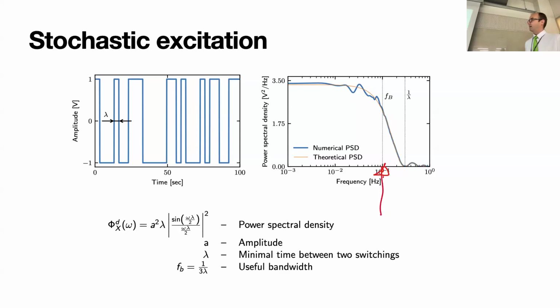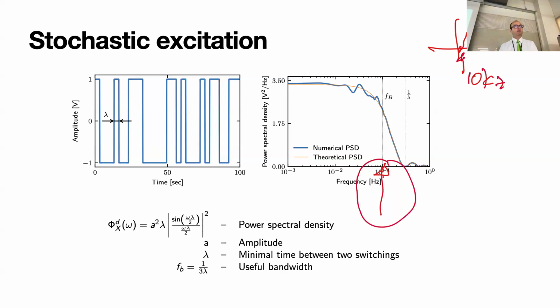What is the highest frequency that we are going to look at? And we can decide this because we know that, for example, for our fuel cell above 10,000 hertz the EIS curve just stops. So the EIS curve may be like this, and here is 10 kilohertz. So we can say that, okay, we can go up to 10 kilohertz and we will capture everything we have in our fuel cell. So all you have to do is, based on this wish, you define this parameter lambda.